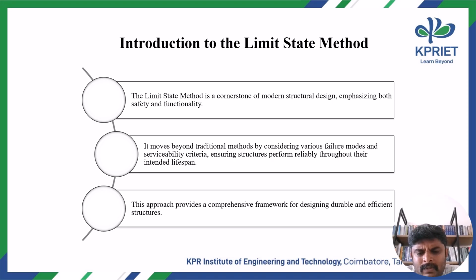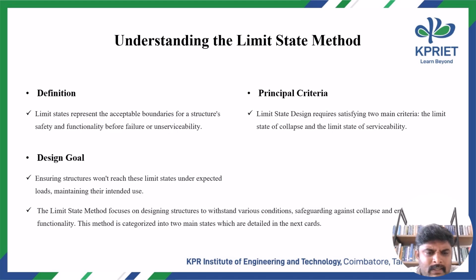serviceability. In the working stress method, we are designing within the elastic limit. Here we are focusing on beyond the elastic limit. And then, understanding of the limit state method. There are two main criteria we are focusing on. First one is limit state of collapse and limit state of serviceability.